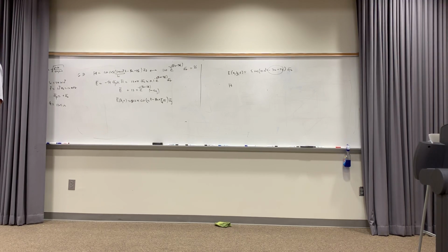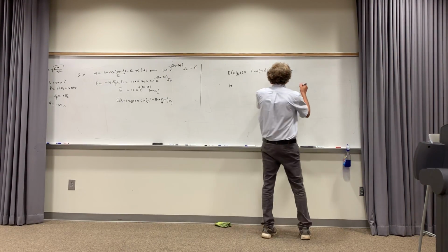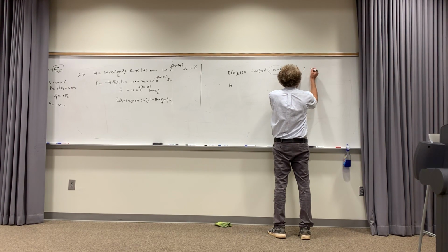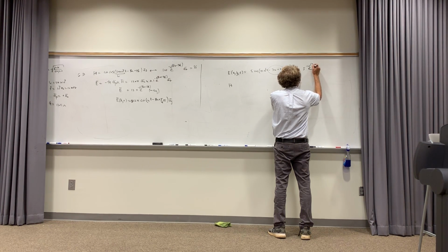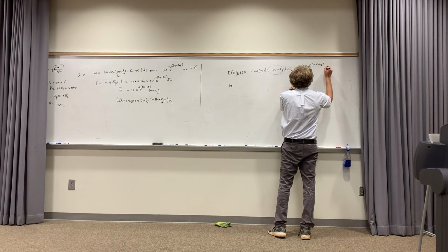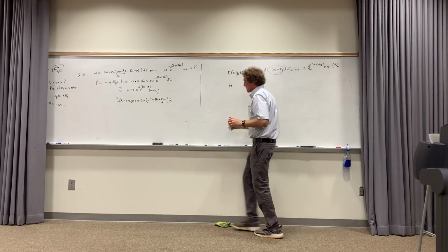Correct, class? Do y'all see this? And you're right. So first we'll turn it into a phasor. If we want a phasor, this is going to be 5, and it's going to be e to the minus j quantity 3x minus 2y, in the z direction. That's volts per meter, the Z field.